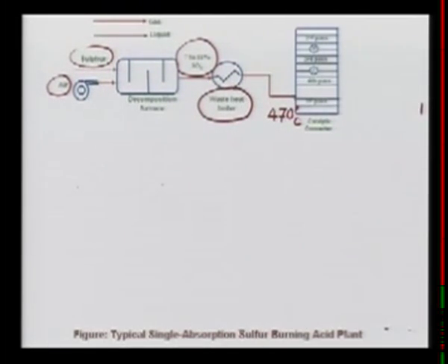So we take it further for the conversion from the SO2 to SO3, but before that we bring down the temperature by the waste heat boiler or heat recovery, and you will see that we almost bring down the temperature to around 470 degrees Celsius. It's about that. Then we are passing through the converter. Okay, and you see here how the converter works. This is a converter tower, but the conversion is done in various phases. As you can see, first phase, second phase, third phase, fourth phase.